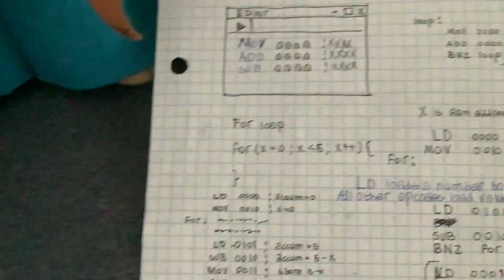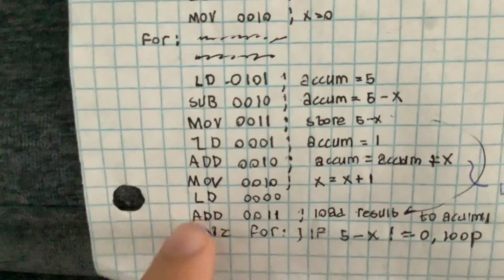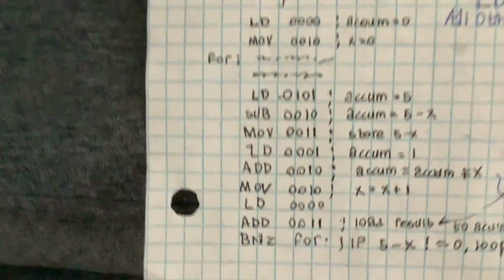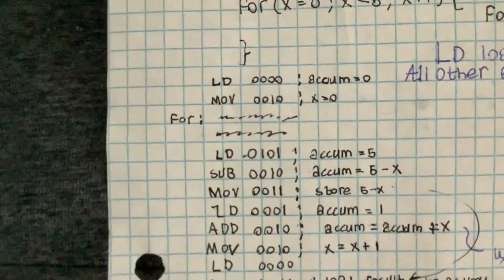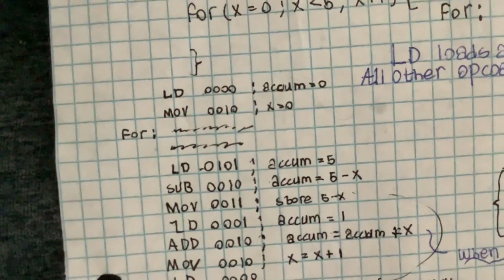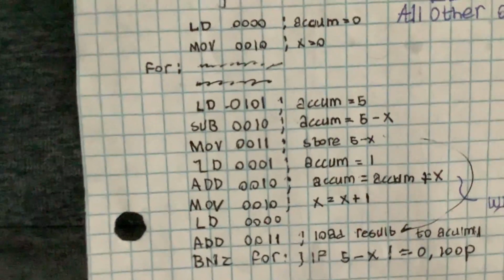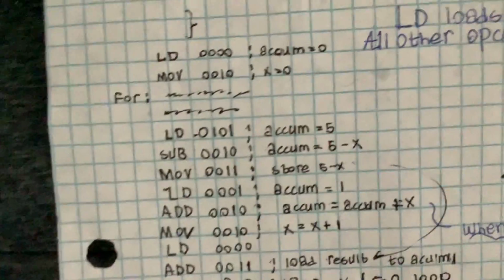implemented. Though I must note that the computer system which we're making is a 4-bit system, and what that means is, well, you have 4 bits of data, 4 addresses. So that means that you might have an issue where as soon as you get 16 of these lines, it'll be too much, or you could go farther, I think, but your loops can only be 16 lines long, which could be a problem, especially since this for loop pretty much takes up that many lines already.